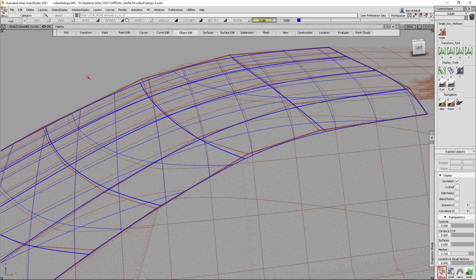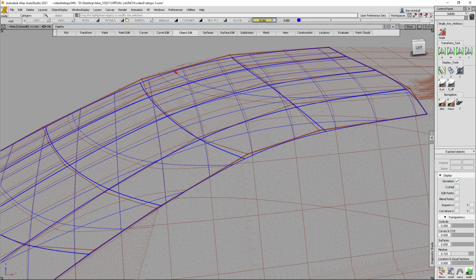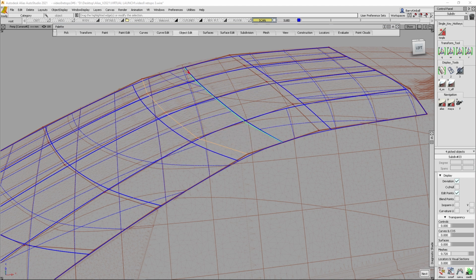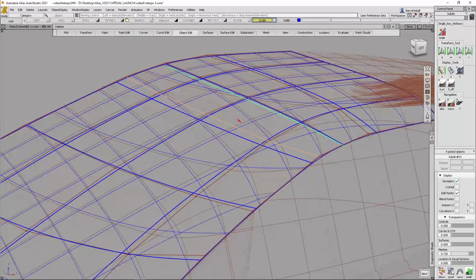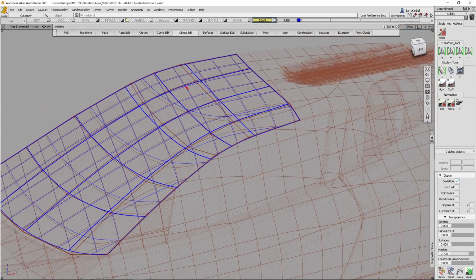What that also offers me is if I'm outside of the retopology tool and I do an insert edge, so I'm just going to insert an edge here. Oops, I'm sorry, that was the wrong direction. I want to insert an edge here. When I let go, if you watch, see right now it's below the scan. When I let go, it gets popped up onto the mesh. Okay, so you can be inside or outside of the tool, and right now any changes that I make to this Subd will be projected onto the reference data.